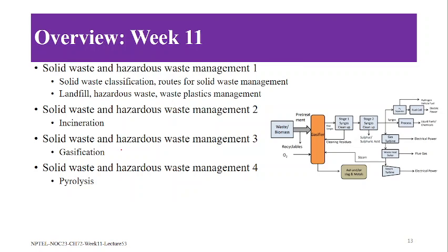And next, gasification. Gasification uses a limited oxygen supply as well as steam to reduce the solid waste as much as possible and generate energy. And next was the pyrolysis, which is basically heating of the solid waste in the absence of oxygen, and which generates solid, liquid as well as gaseous components.